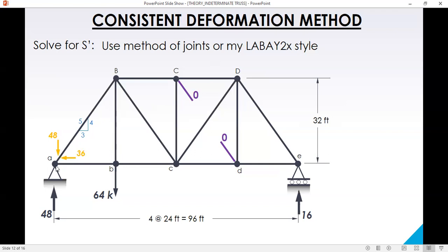And then, to determine the magnitude, 48 over 4, 12 times 5, 60. So, member EB is compression, that's negative 60. And to balance this 36, the force of member AB must be 36 also. And since this is directed to the left, AB must be directed to the right. So, tensile, so it's positive 36. So we can now say that joint A is in equilibrium.